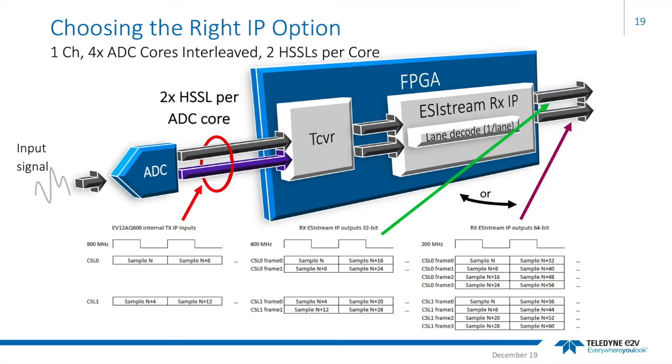In these timing diagrams, you can see how an 800 MHz data clock at the transmit end of the link within the ADC is received by the transceiver within the FPGA as 4 data words at 400 MHz per lane. With 32-bit data framing, that's the characteristic shown in the lower middle of this slide. Or in the case of 64-bit framing, 8 data words per lane, seen here on the right-hand side of the image. This basically summarizes how data frame width impacts the data processing system.